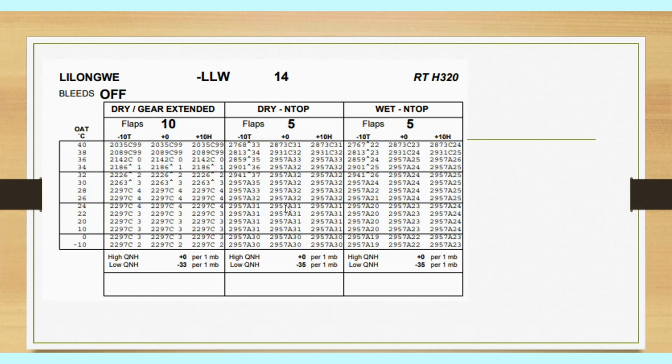So these are the weights or the masses we can carry. The letters here, the C's and the A's, and the numbers that follow them, 31, 32, and so forth, we'll discuss in the second part. The C's and the A's are limit weights; I'll explain later if you don't have it already on your systems. And these are the speeds, but we won't touch on those right now. Our main focus for this presentation is to work out what maximum mass we can carry, and how to reduce the torque, so you can reduce the takeoff power to accommodate the engine lives.